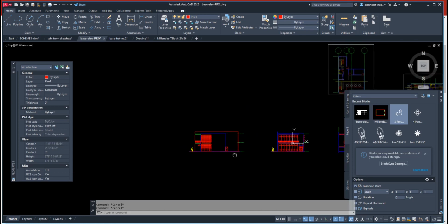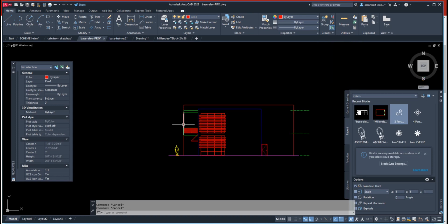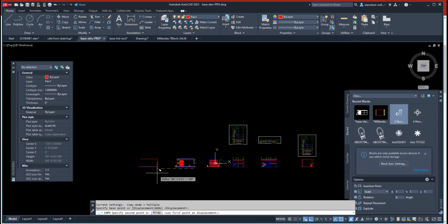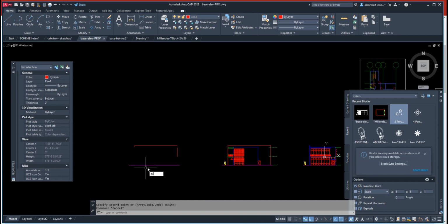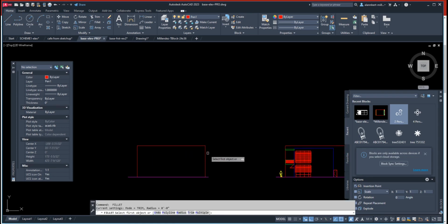For our left elevation, remember that it's just the outline of the building, so we're just gonna copy this, and the floor and pull that somewhere here and simply just extend those lines down here. Let's do a fillet. There you go. And that's just the outline for the building.